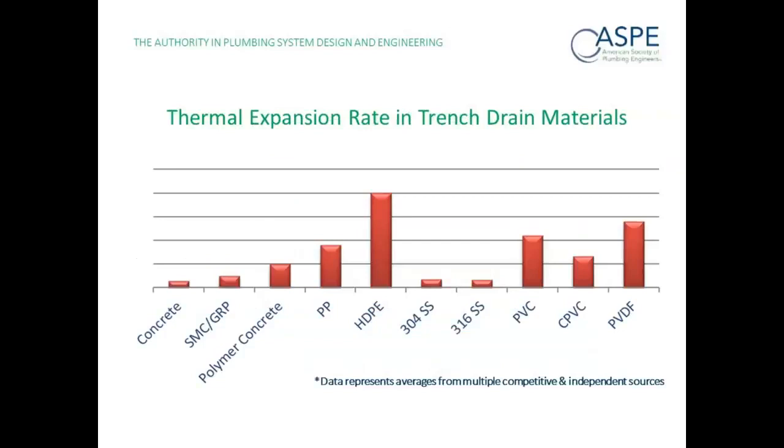So I think the most important slide here as it relates to the flooring and the drainage is the thermal expansion. Scott Garska, talk to us about thermal expansion and the significance for drainage and bacteria growth. Sure. One of the things that we see all the time is somebody will specify a drain and specify a floor. Unfortunately, those materials may be incompatible, especially if there are elevated temperatures. As there's heating and cooling going on, you're talking about two rigid systems that expand and contract with different thermal rates of expansion.